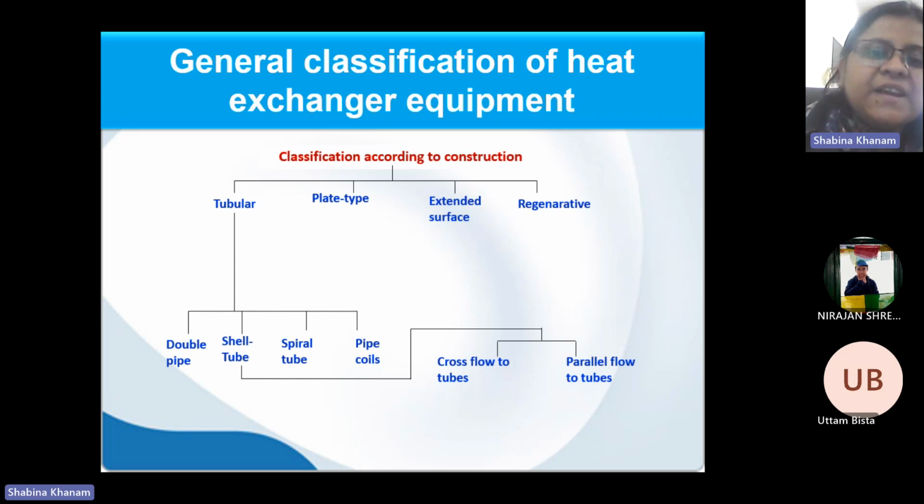But in a common heat exchanger, when I have significant length, I have the cross flow, and once I have the cross flow, the fluid will move in this direction, so there will be parallel flow as well. So usually in a shell and tube heat exchanger, I have cross flow, co-current flow, and counter current flow. All three exist together. We will consider all these flows later on in detail. So that is about the tubular type.